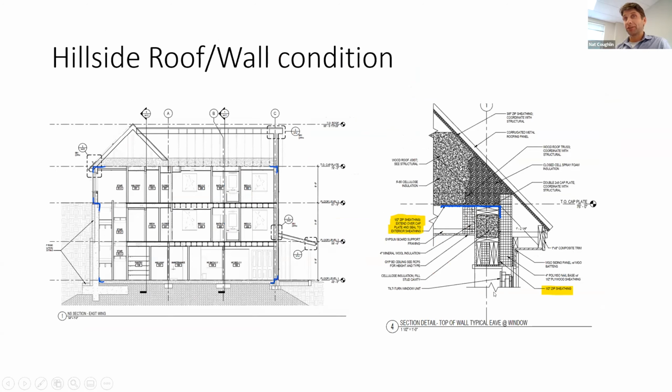At Hillside, similar to at Waring, same thing. This is the shape of the building, and you can see at the corners in blue, for our own use, we drew how that air barrier ties together at those corners. And in this case, because we were buried into the side of a hill, we actually had an interesting detail where we were connecting to the retaining wall midway up the building from the outside of the sheathing into this big retaining wall. And then the retaining wall concrete, which has waterproofing on the outside, really kind of is our air barrier there. And then we pick it up down at the bottom.